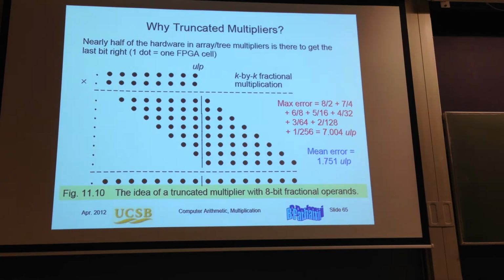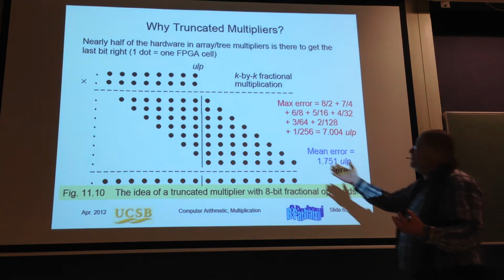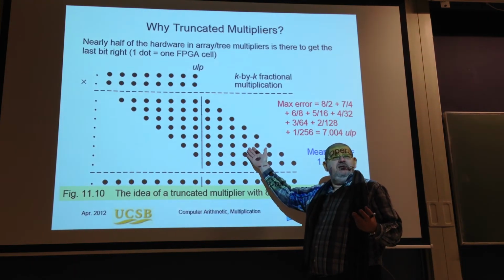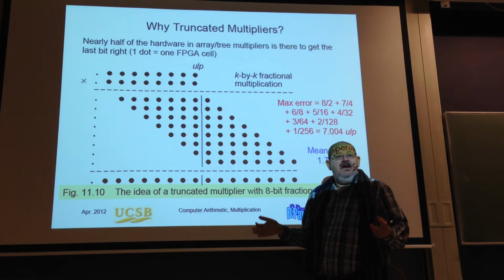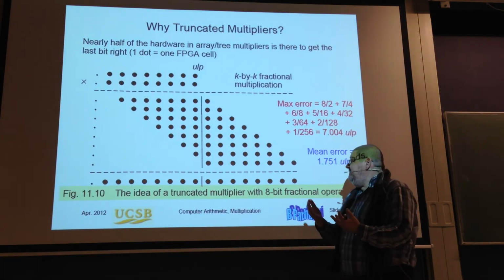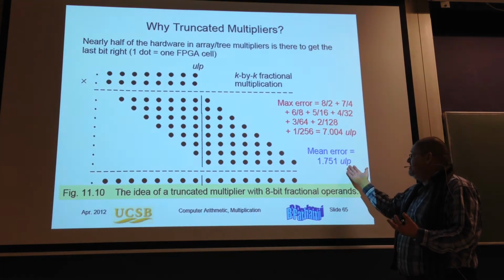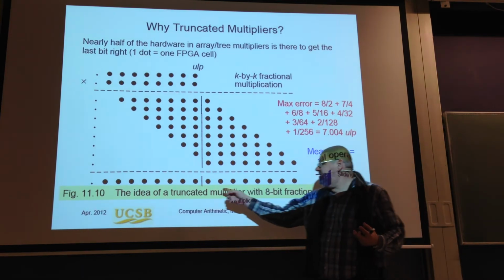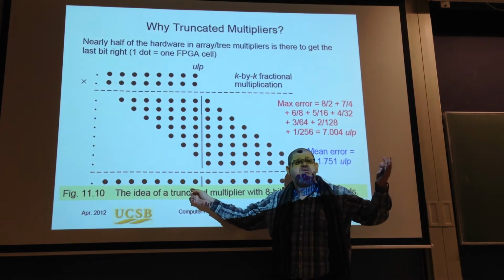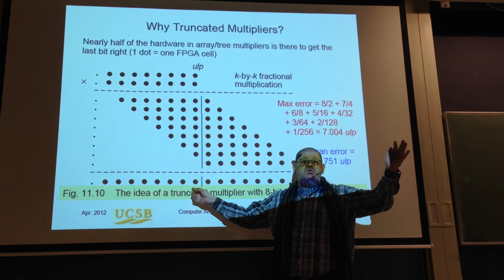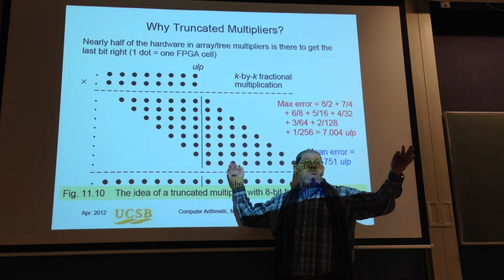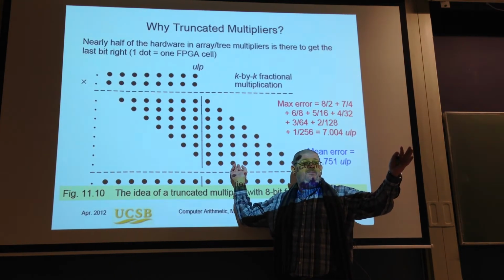The fact that this is in the fractional part will not preclude me from applying full adders here. Full adders don't see that. But my effort will give me a result which is contributing at most, let's say, less than 2 units in last position. And I will spend a lot of hardware in here.